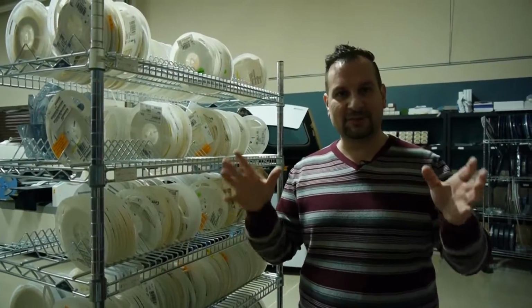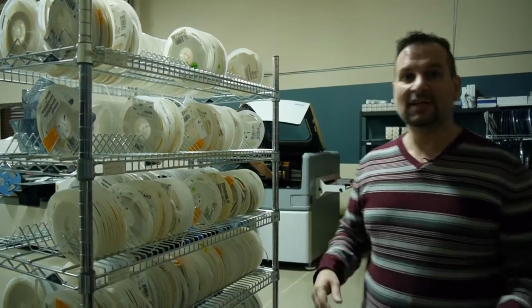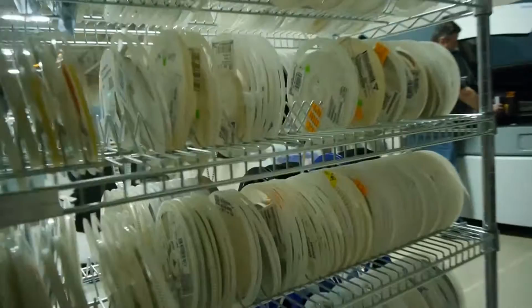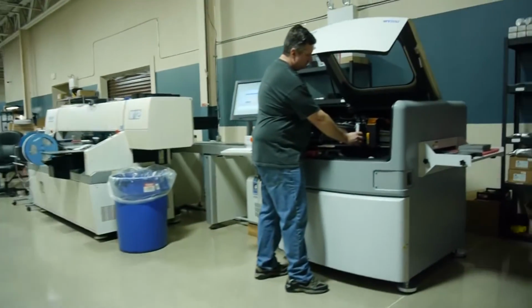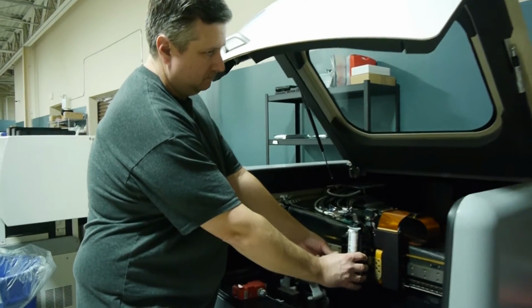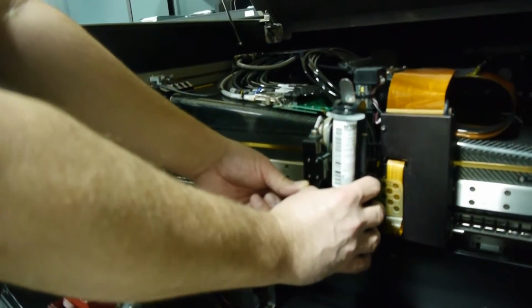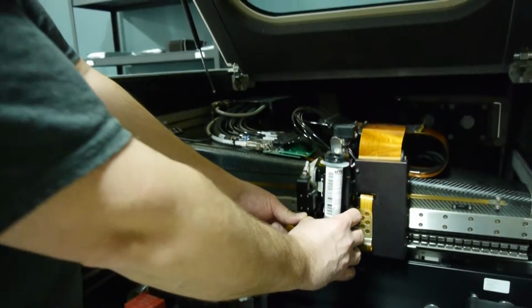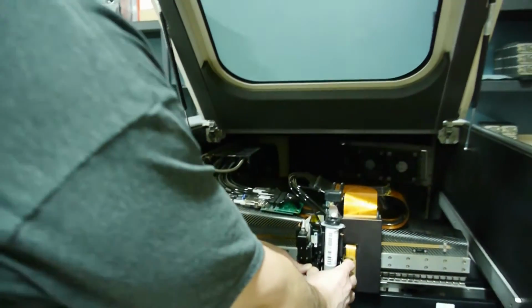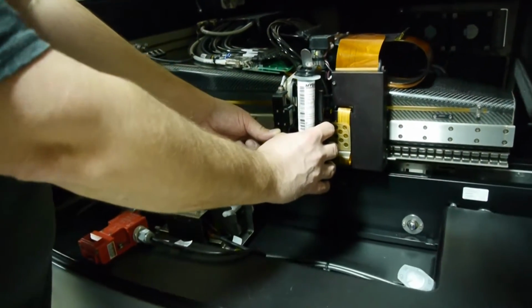Now that we have designed the circuit, we've verified everything is okay, we're ready for production. This is where production happens. These are the raw components. They come on reels. Some of them come on trays. The next thing we would need is the raw circuit boards that go into this first machine. This is a pretty fancy machine that actually is a printer that prints solder on the circuit board. It's a jet printer, basically. Instead of putting ink on the circuit, it does soldering on the circuit.